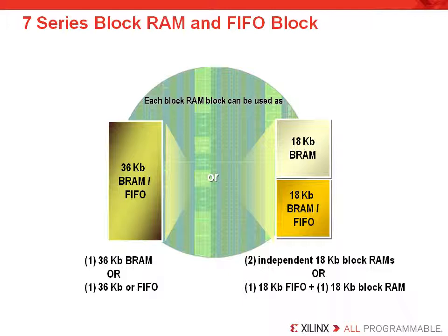This means that you might have extra memory resources that you can use for finite state machines or use for FIFOs when transmitting data between unrelated clock domains, for example. So just make certain you try to think out of the box because you might have block RAM left over that you can use if you're creative. Now you should also note that unlike Spartan 6, the Virtex 6 and 7 Series block RAMs allow you to build a FIFO out of one of the segmented 18 kilobit memory resources.